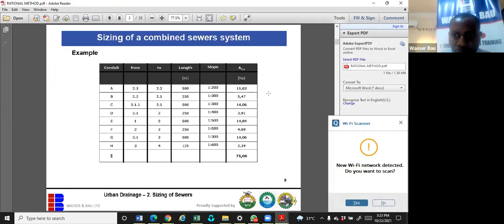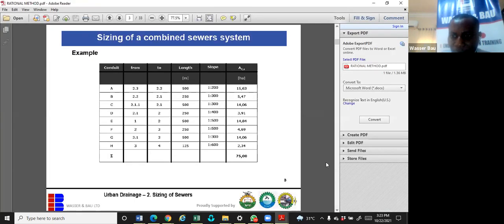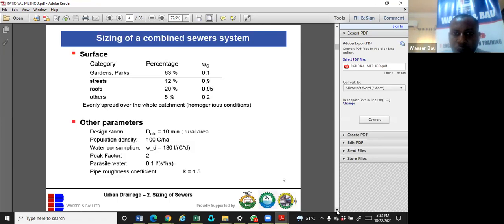you can see we have put them in a table in the proper perspective. All this we did yesterday, how to generate this. But for the benefit of those who were not here yesterday, the first thing you do is you characterize the catchment. Based on the composition of the catchment, you assign the corresponding peak runoff to them. At the end of the day, you use the weighted average to get the average runoff.